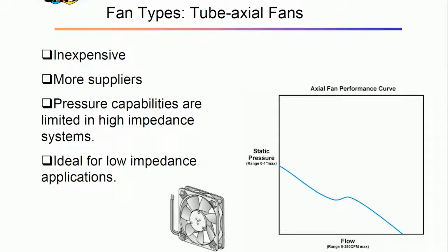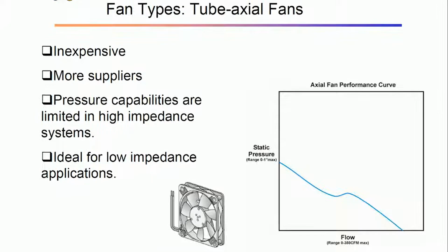early on in one of the lectures I mentioned to you that there are these fans where they mention the static pressure, saying typically it will give you about 1 inch, meaning when no flow is there it gives about 1 inch, and they also mention a delivery, saying it gives 100 CFM, 200 CFM and all that. Main attraction is they are inexpensive.